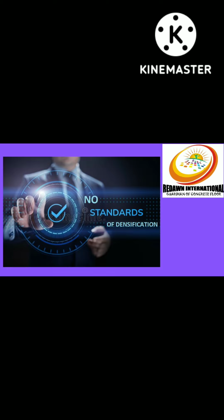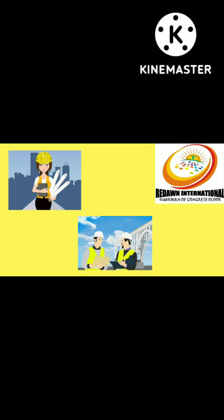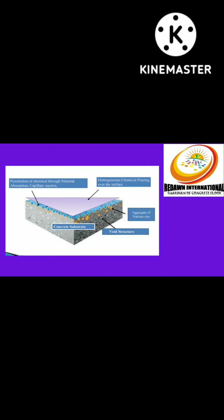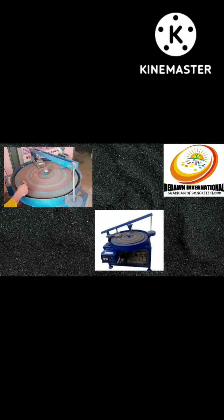There are no real standards for densification. Owners, architects and ultimate users need to understand the difference between densification and polishing. Both are different and have variable characteristics. A good densified floor need not be polished. Complete calculation of floor consumption will guide owners and architects. However, properties such as abrasion resistance and surface hardness are considered indicators of densification.